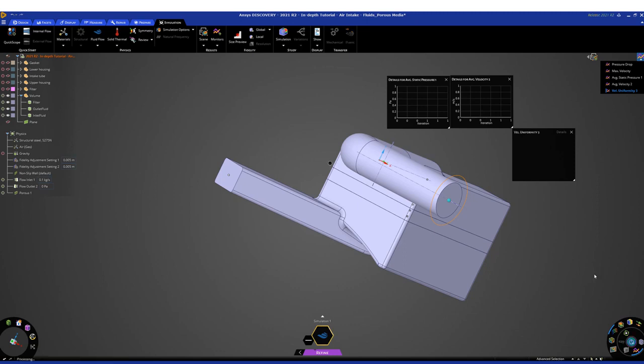As the simulation starts, you can see this simulation information display of Ansys Discovery and a green line showing the progress of the solver. After 50% here, you can start looking at the mesh because that means that the mesh generation is finished. And you can also see some other information here regarding what kind of simulation we are doing. Here it says a steady state fluid flow analysis.